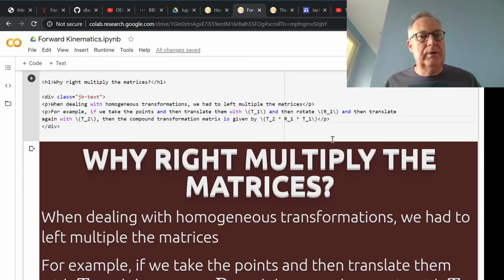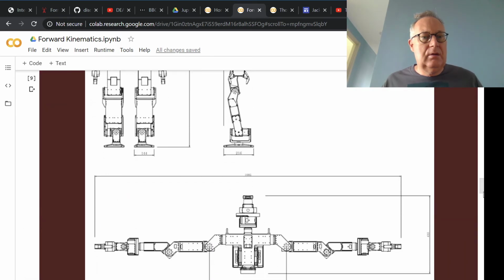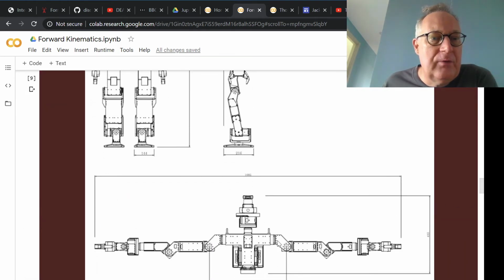Then we move it to the next joint, we rotate around that point in order to align it. So here we move first to the shoulder, then align the coordinate system here. Then from here we move to there, then rotate the coordinate system, but it shouldn't be rotated around the origin, it should be rotated around its current position.